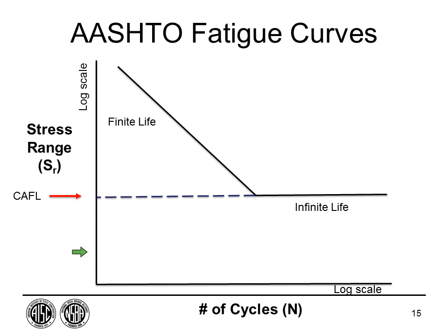The difference is the bottom flange will eventually break in half because everything's in tension. The top flange will crack, and then it stops. It enters a compression residual stress zone. But the basic question is, we would not treat them any different in AASHTO unless the live load stress range is always hidden by the compressive dead load stress.